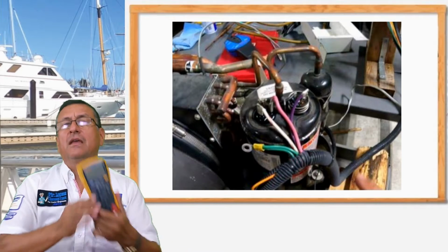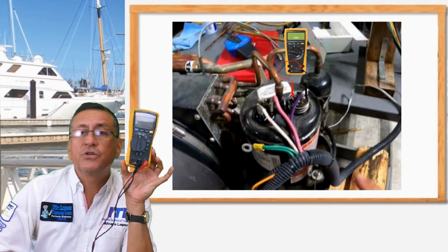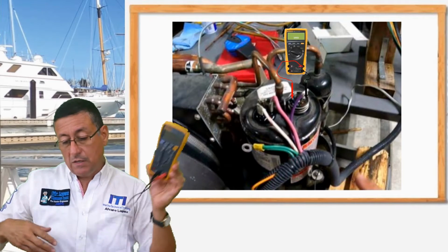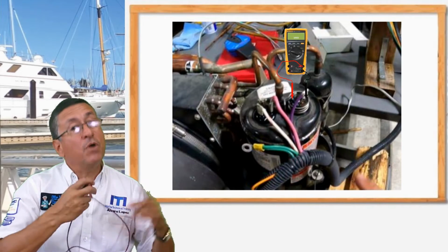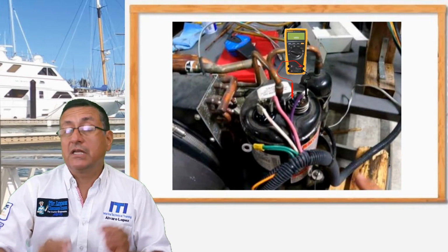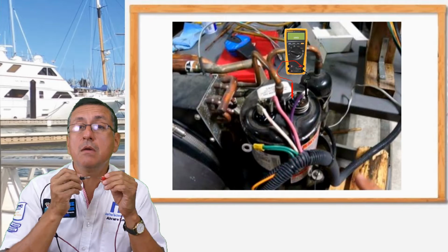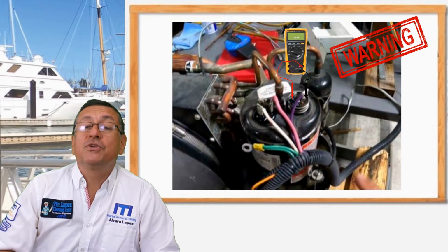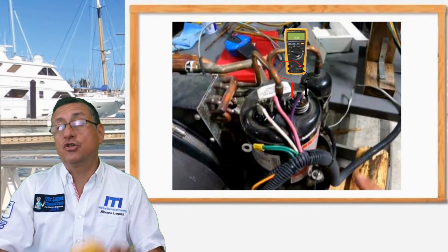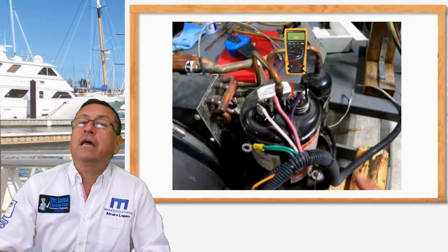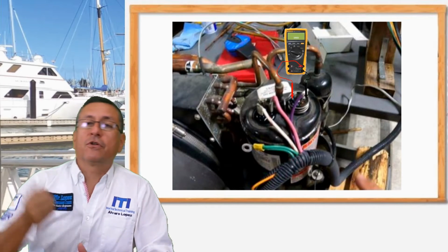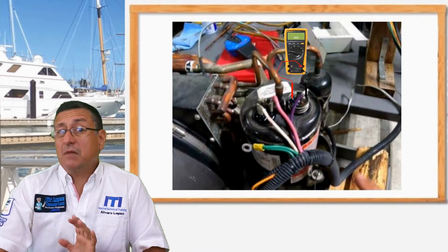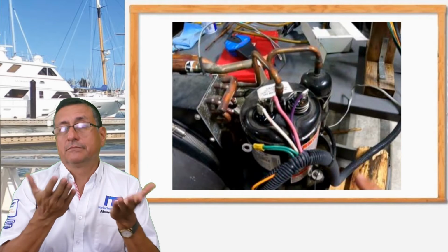What is the meaning of that? If I use my multimeter in the ohms option, the sound, beep, continuity option, and we check in between both terminals of the switch, it's supposed that if the temperature is low, you have continuity. Beep. Of course, when you use the multimeter in ohms, the circuit should be off, no power. If not, you damage the multimeter. Alright? Turn off the main breaker coming from the AC panel, no power, and check continuity in the thermal switch. If the thermal switch at ambient temperature is open, this is the problem.